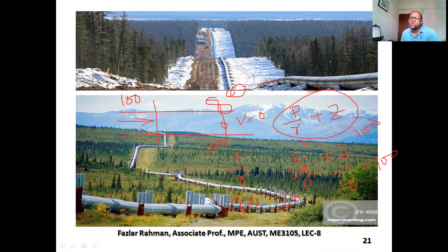So how much will the pressure be then? It will be the same, or it will increase. You see, Z is 10. So this is 10. Now to make 100, this value has to be how much? This value has to be 90. So you see, the pressure energy at point 1 was 70. At point 2, it became 90, because the total energy always has to be 100.